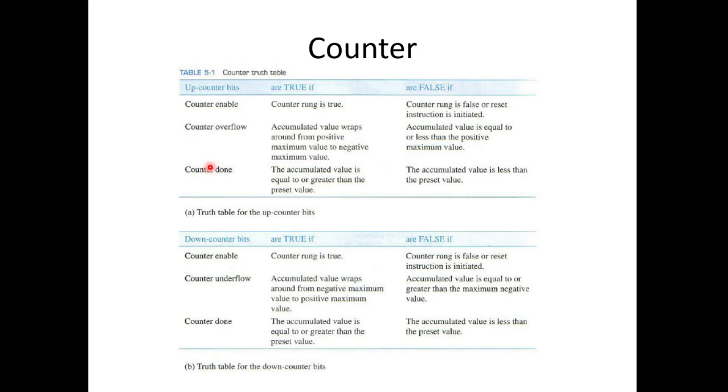If you do not have a mechanism in the program to stop the counter after it finishes counting to the preset value, then the accumulator value can go up and up all the time. It is a 16-bit memory, so it will hold only the maximum number a 16-bit word allows. If we still keep on counting, there will be an overflow bit and it will be flagged when the accumulator value reaches its maximum value.